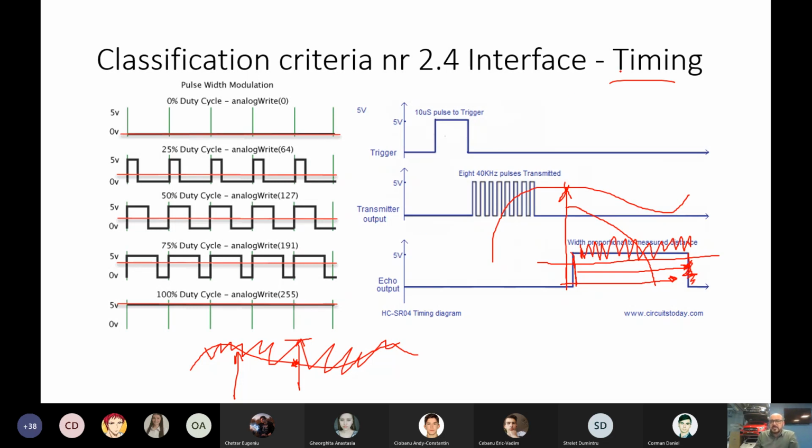This signal means that we are sending the value in time. Sending a lower value, we will have a shorter pulse, and a higher value, a longer pulse. Depending on the system, we can have different resolutions of the signal, but in this case we protect against the noises.